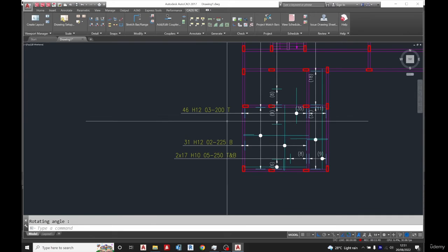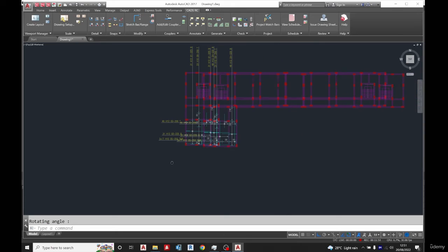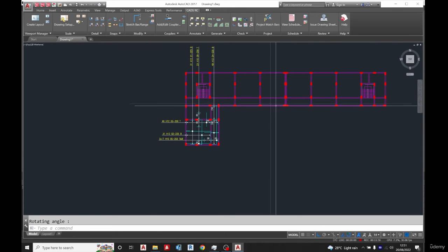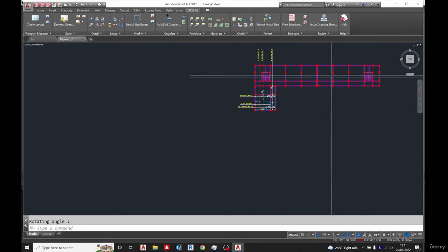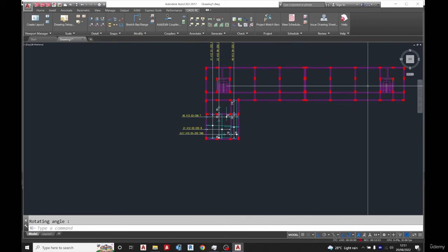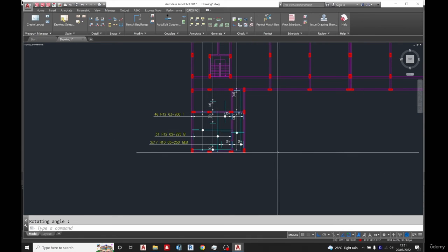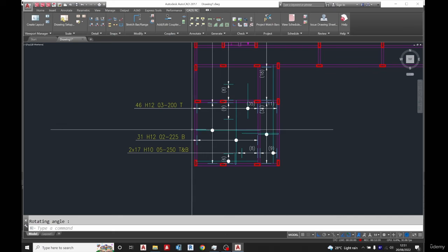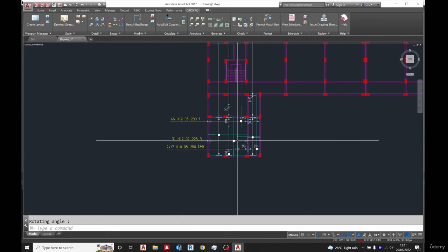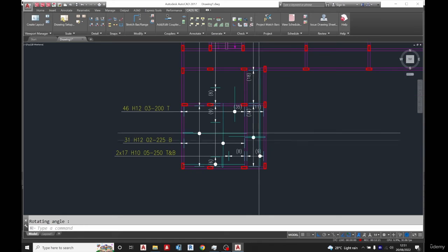Another rule in detailing is that you make your detailing as simple as possible. Don't make it so cumbersome. You get? So what I can do is detail this place and say "similar to", because this place is a mirror of this place, so we can do that already. So you can see, the basics of detailing, we've gotten it already. There's no other issue. I can also use the same reinforcement, but because I've multiplied it by top and bottom, I don't want us to confuse each other at this point. So you can see this.